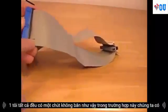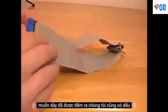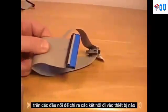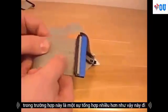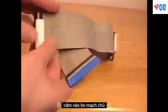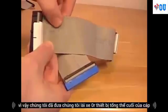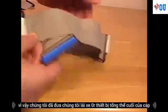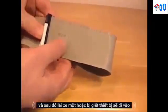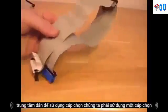A couple of items on a cable select cable. One of them will have a little notch out of it. In this case, one of the wires has been punched out. We also have markers on the connectors to indicate which connector goes to which device. This one says sys board, so this plugs into the motherboard. The connector at the end of this cable supports drive 0, so we would put our drive 0 or our master device on the end of the cable. And then drive 1 or our slave device would go on the center connector. So if we're using cable select, we have to use a cable select cable.